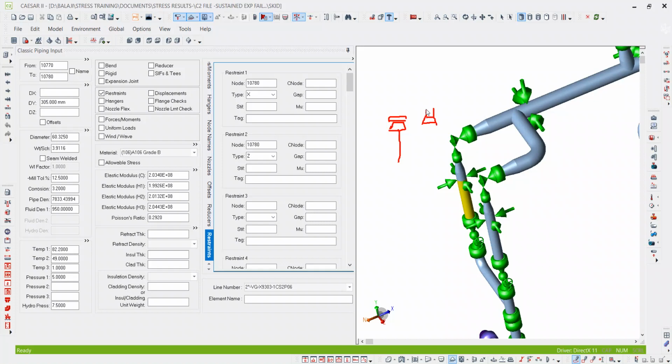So a 100 mm spool you can introduce. After that, you add the flange. Then your stresses will reduce for the expansion case. This is a general practice. If 100 mm is not sufficient, then you have to increase the spool to 200, but with the approval from the process team. So you need to get the approval from the process team regarding this, and also from the layout team.